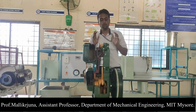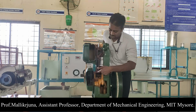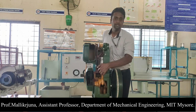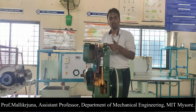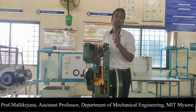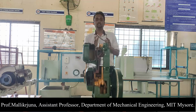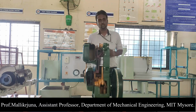During the suction stroke, piston will be at top dead center, and during the starting of the compression stroke, the piston will be at bottom dead center, and during the starting of the power stroke, again the piston will be at top dead center, and during the starting of the exhaust stroke, piston will be at bottom dead center. So these are the various positions of the piston at various strokes.